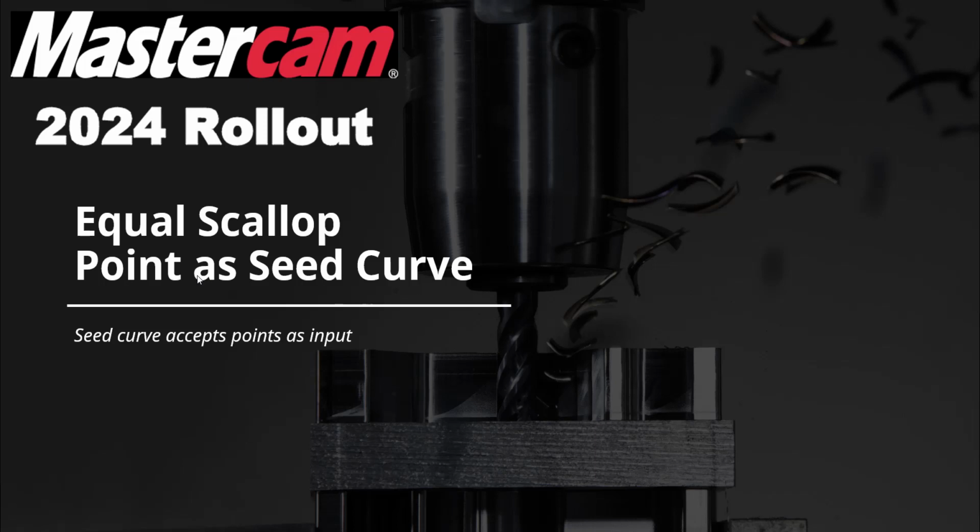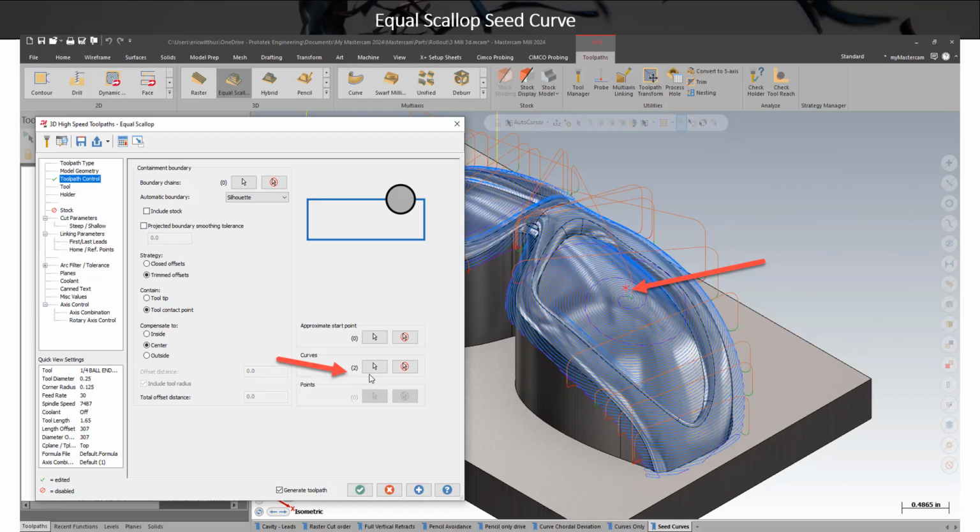The equal scallop uses all your cores to crunch at once, and the scallop toolpaths are a bit bigger. And sometimes in scallops, you get some distortion in your patterns, and the equal scallop added some tolerances to help clean these distortions up. What's new in this version is the seed curves. You can now use point geometry.